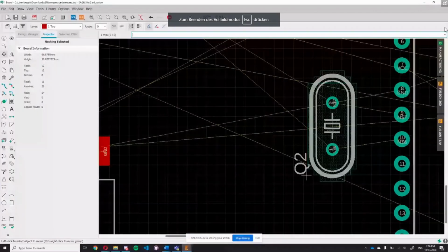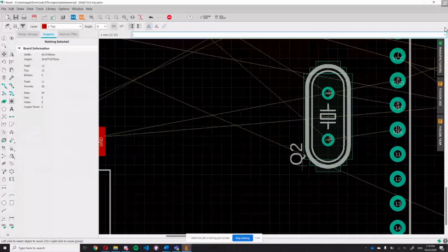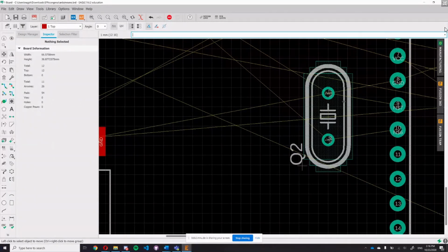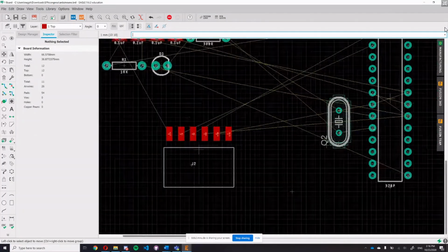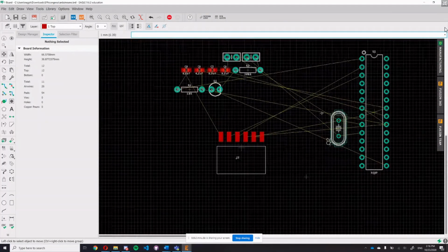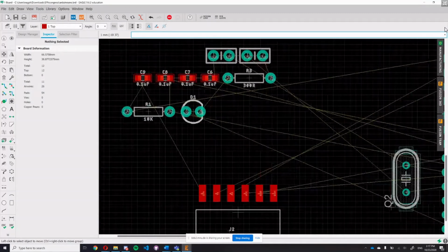And an important thing to remember with oscillators is the traces. I'll explain what a trace is. Basically a cable. So here is going to be a cable connecting these two components. So the traces need to be as uniform. Now you can see a bunch of these components, and you have these yellow lines, and you probably already figured out that the yellow lines represent what needs to be connected. So now we can lay out the other steps.